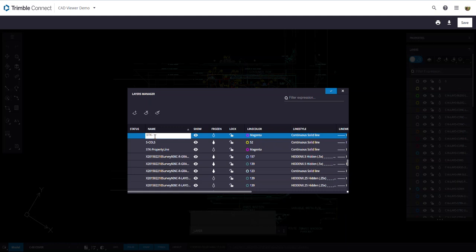Now we've got 1A curbing and 1B curbing. And we also have top of curb and face of curb. So we're going to do 1A dash, top back of curb, or TBC. So we'll just do TB curb. So basically that means top back. You can spell it out if you wish. We're going to change that 1A to, let's make that a blue color.